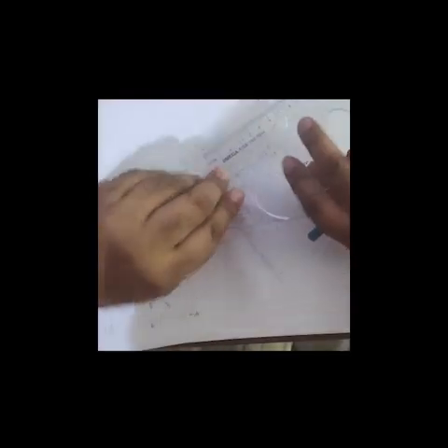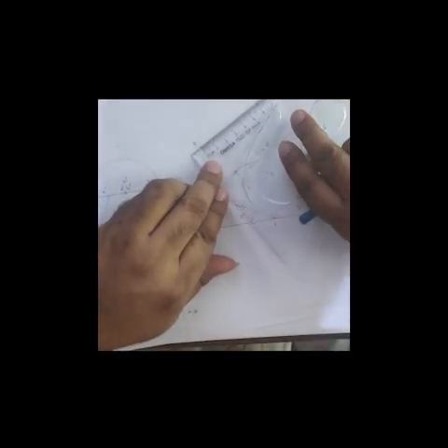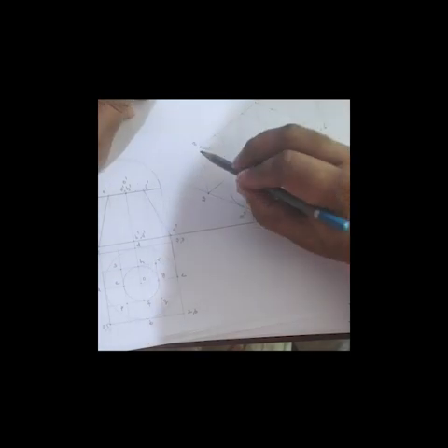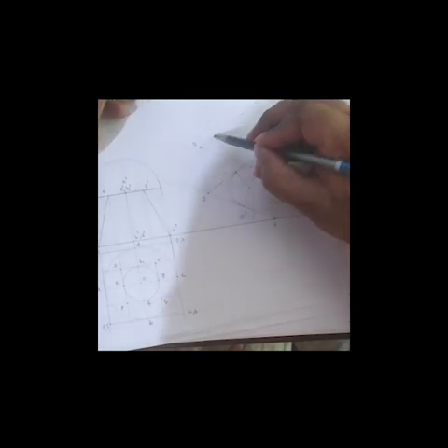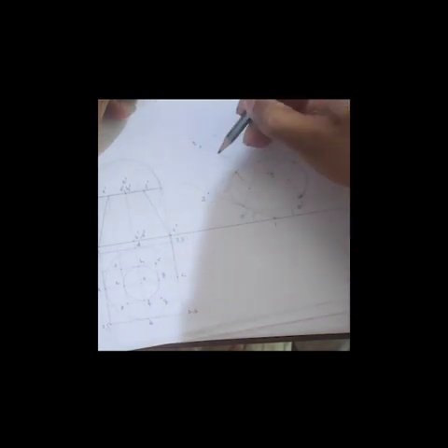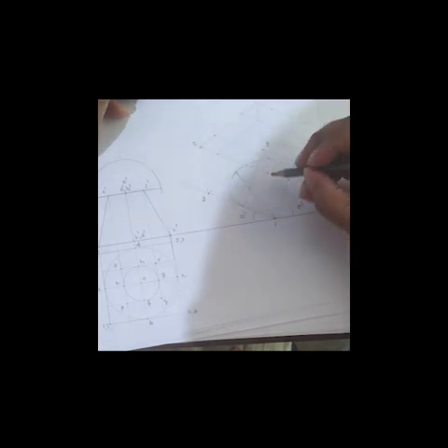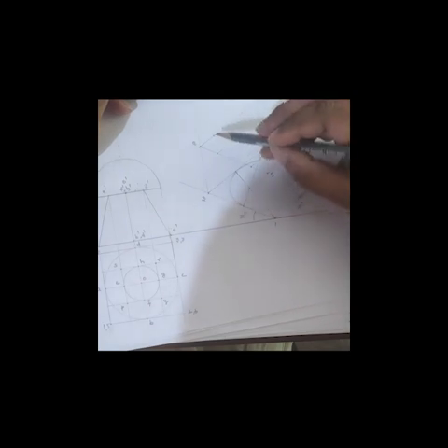So here we have isometric view, so you can directly take that distance and mark 15 mm over the surface. Take 15 mm and mark this dimension. Take another 15 mm and mark this dimension. Take 15 mm in this direction and another 15 mm in this direction, and similarly you will get some points.